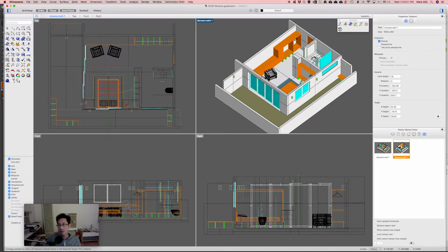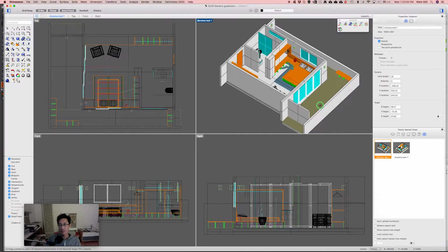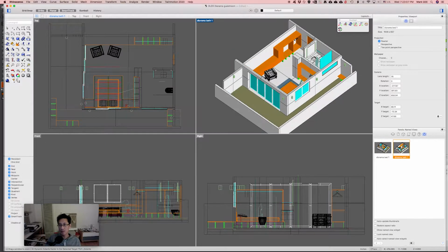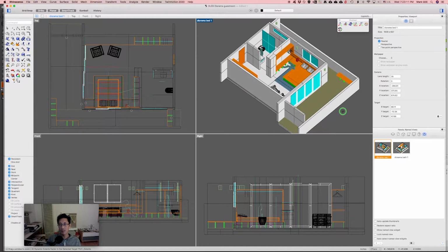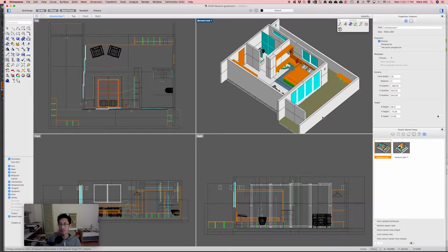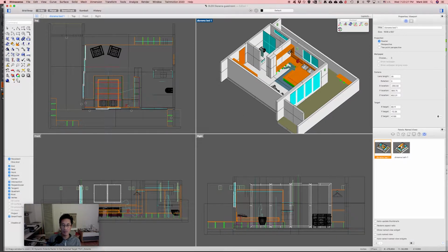And the two views are also at basically the same angle. Same axonometric angle, right? So you adjust those to try and get basically the same angle, so that when they appear on the page, they're cohesive in the angle. And so here I'm making a new saved view using the named views panel.